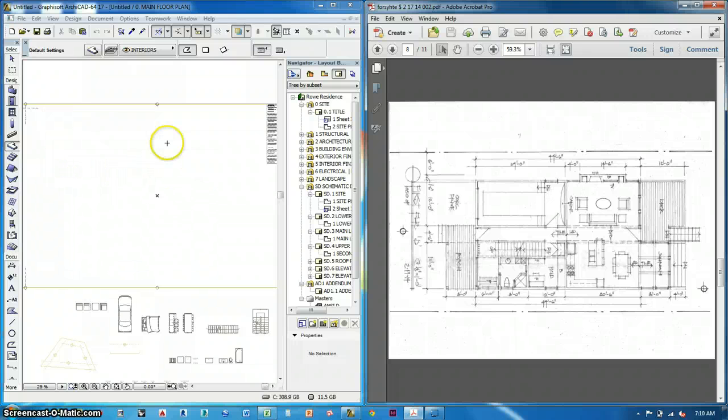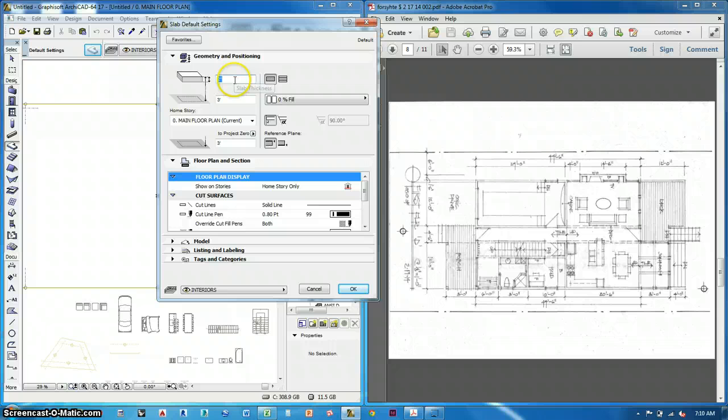So I go over here, and I'm on this form of geometry, which is the polygonal, it's a nice word. And then I want to make sure I've got the settings right for this, so I can click here to make sure I got the settings. And the slab on the first floor we'll assume is a 16-inch floor truss with 3/4 inch plywood on top, and we'll set it at 0, right? Because we'll set the project 0 at the top of the main level subfloor. At the top of this floor will be the 0.